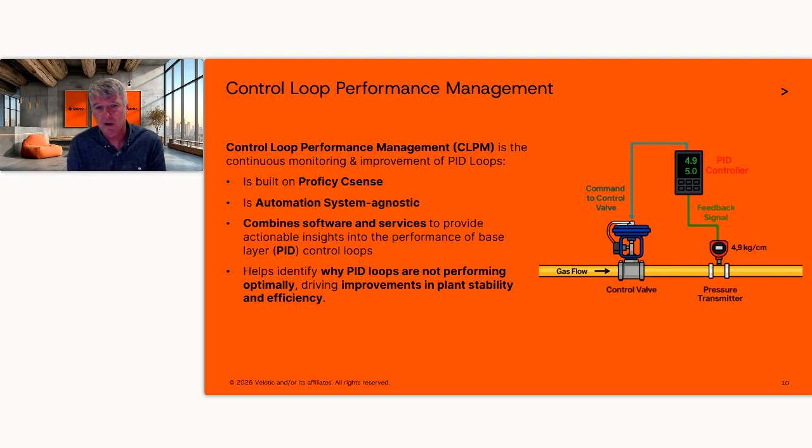So a couple of things that we have is the set point, which would be like the 60 PSI. We also have the process variable, which is measuring what our current value is. So 60 PSI is our set point, and we're currently at 58 PSI. And then you have the manipulated variable, and that's basically this valve position. So how much am I opening and closing the valve? As my pressure drops, I might open the valve more. As my pressure increases, I might close down the valve.